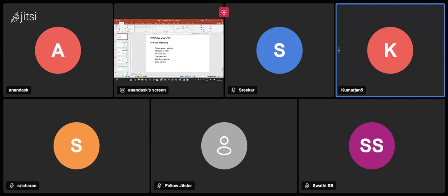The trace window is one of the key things for any CAN bus. It will give you the complete events happening. All the events come in chronological order with respect to your DBC file, your database file, so you know what message it is populating and what message is updating, and we can examine those trace values perfectly. It doesn't have any error frame. So with this logic behind it, we can analyze with the help of a graph window.